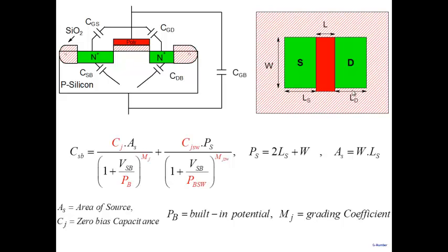So after a schematic design, you have to do a layout design, where you specify how these things are done. But since in this particular course we are not going to do the layout, as a first order approximation, what we are going to assume is that LS is typically equal to L. This is not true in practice. As I said, you have to do the layout, but as a first order approximation, you can assume LS is equal to L.